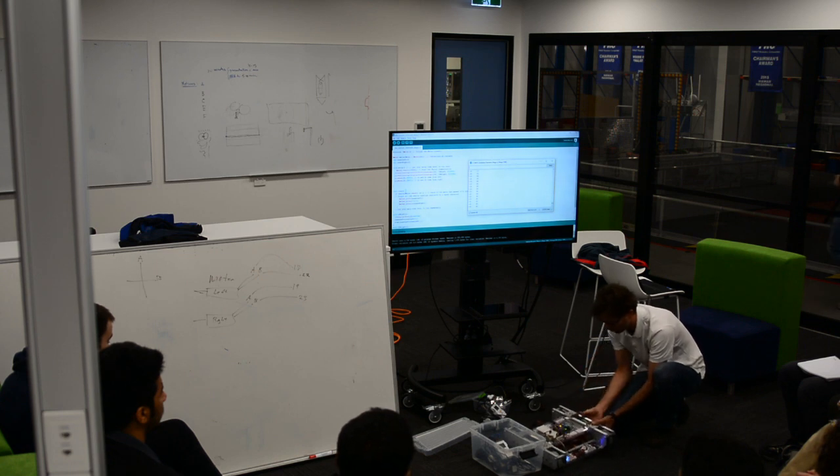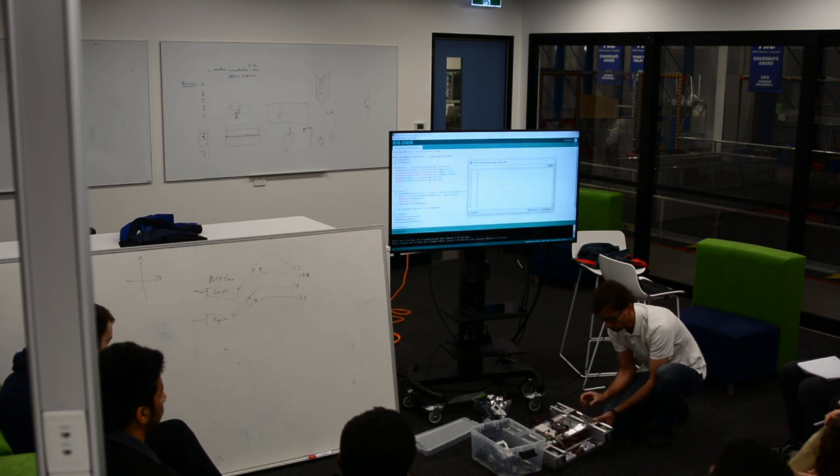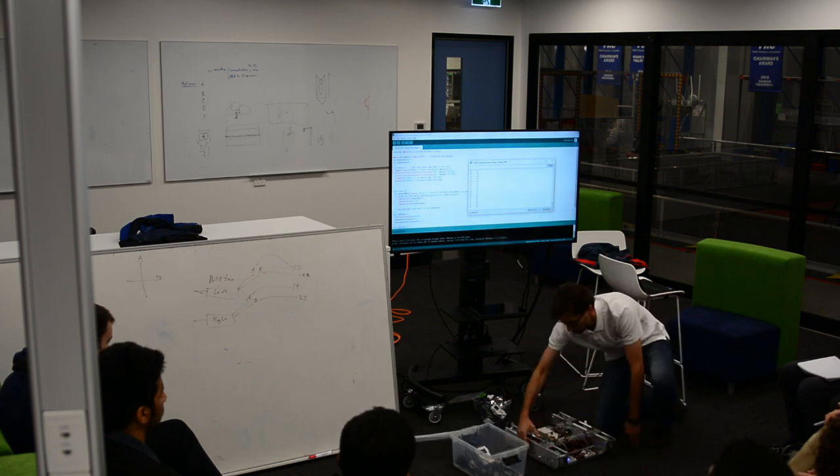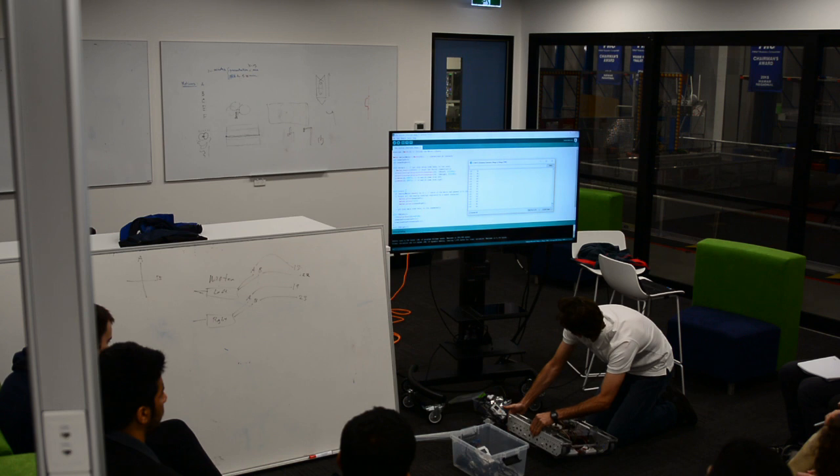One thing now that I know you guys are software, you don't have to worry about this. The grub screws get loose on this pretty easily. So if you pick up your robot and you give it a wiggle like this, and there's a lot of wiggle, that's a bit more wiggle than there should be already. That means the grub screws are getting loose and the wheels are losing contact with the shaft. This one probably is still pretty snug. See how much wiggle we got in this one? Yeah, it's a little bit less. Not so bad. But you'll see that wiggling won't change that because I'm not actually moving the motors.